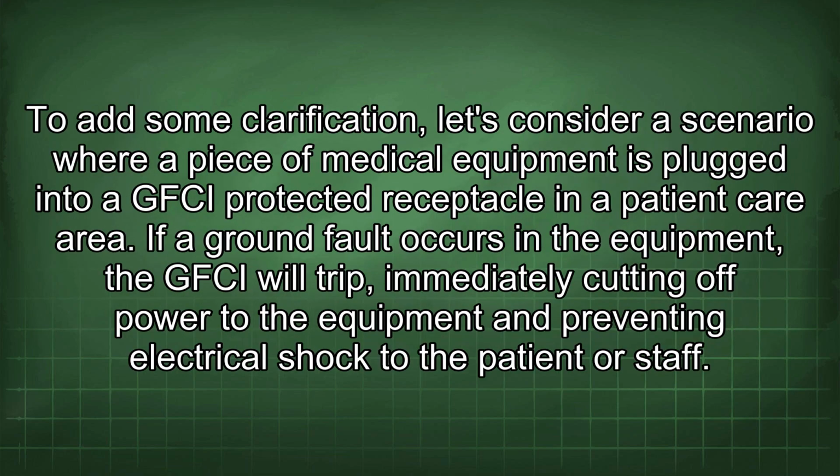To add some clarification, let's consider a scenario where a piece of medical equipment is plugged into a GFCI protected receptacle in a patient care area. If a ground fault occurs in the equipment, the GFCI will trip, immediately cutting off power to the equipment and preventing electrical shock to the patient or staff.